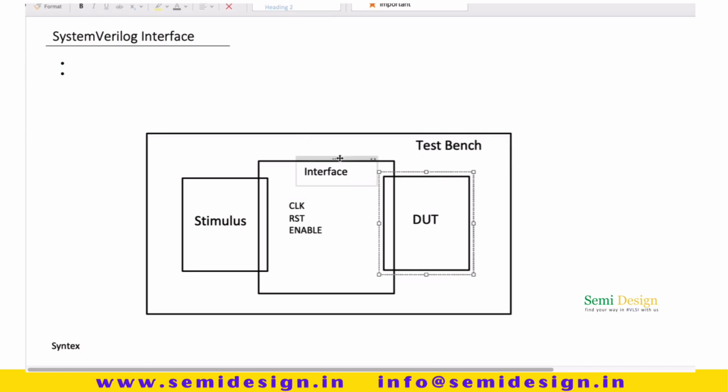So basically we are creating a block which holds or contains all the signals declared in a design, and which connects the design and the stimulus in the testbench. From this we can understand what an interface is.